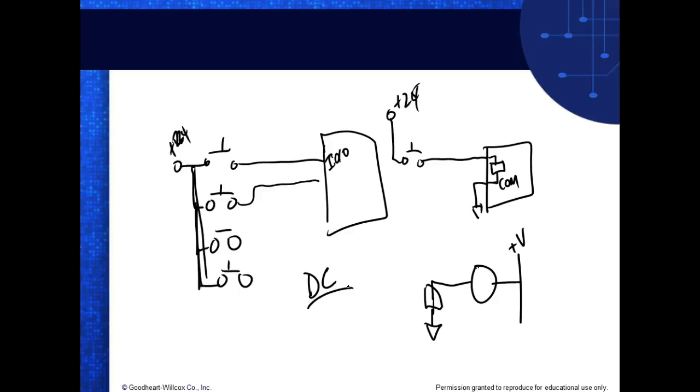The only problem with relay outputs, they have a lot of advantages, but now you're switching back over to an electromechanical device, right? They use these little reed relays, which means contacts could freeze. If you short them out, your contacts could weld together, and then you've lost an output. So that output right there is going to be a physical output, that motor right there. Yeah, this would be just a load that we're going to use one of our output ports on. I mean, it could be a light bulb.